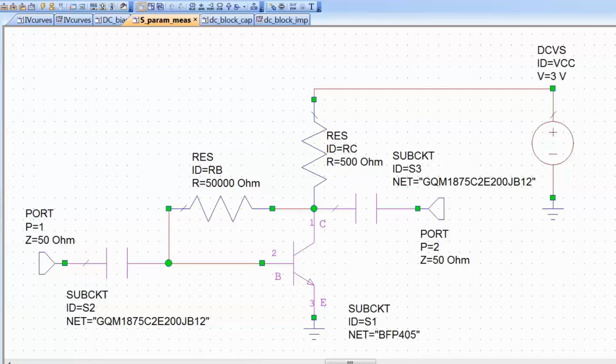If we put an inductor in series with each bias resistor, when the microwaves try to flow back into the bias network, they will encounter an impedance which is very high, because the impedance of the inductor is proportional to frequency, and hence they won't be able to flow back into the power supply. However, the DC currents will see the inductor as a short circuit. So this seems like an arrangement that might work.